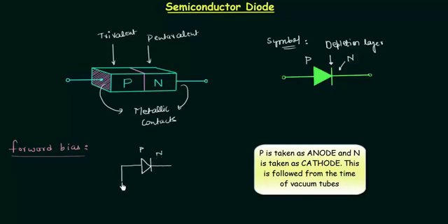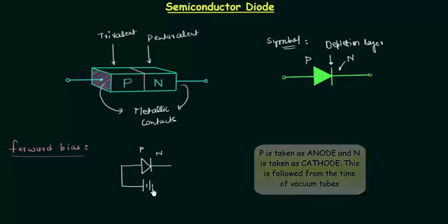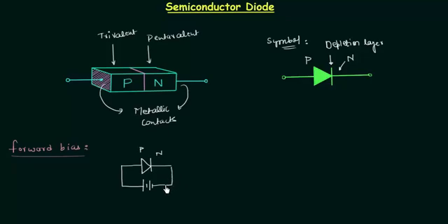So this is how the forward bias circuit looks when we use this symbol. Let's say the applied forward potential is Vd, and the current through the diode is Id, and Id is equal to I majority, the current due to majority charge carriers, minus Is, where Is is the reverse saturation current.